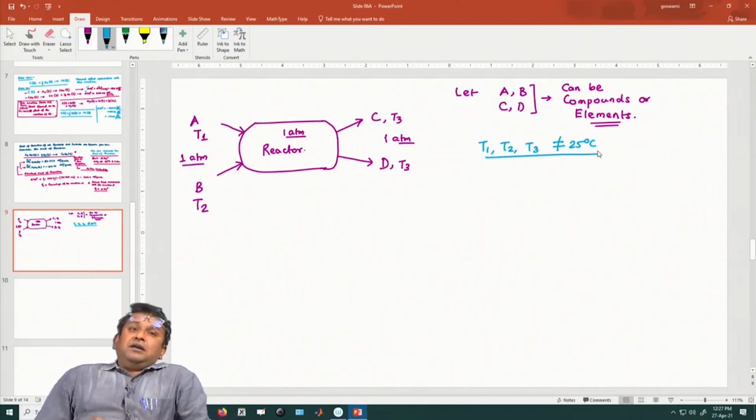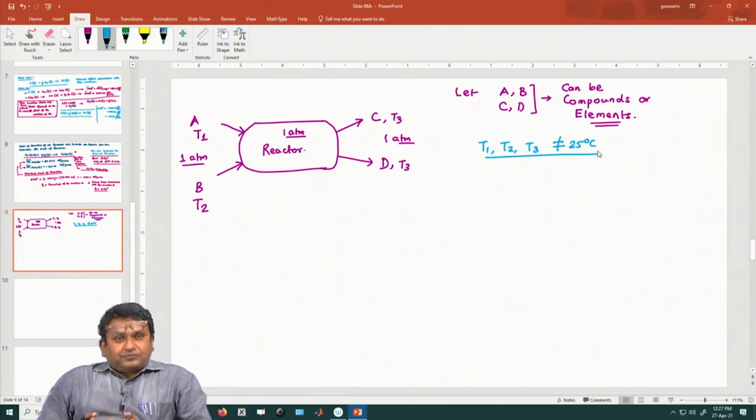The reaction may become slower with time, or if there is continuous generation of heat, the reactor becomes too hot and there can be potential material failure. If the reactor becomes hot, there are issues associated with insulation, some rubber lining may go bad, and all these things can happen, right. So, a lot of reactors actually work under isothermal conditions. So, you have to maintain the temperature.